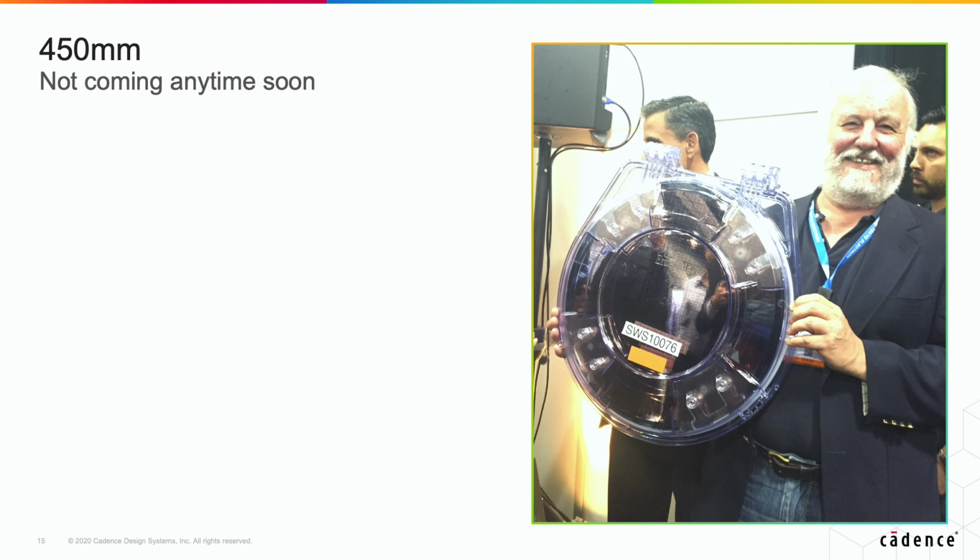There's an expectation, which is not happening anytime soon, but I've got a neat photograph of me holding one, of 450, which is huge. That's an 18-inch wafer. But the equipment for building it is so expensive, and the volume required for a fab to use those wafers is such, that nobody expects it to happen anytime soon. And it requires the whole industry to move. It's no good just one equipment manufacturer building 450 millimeter equipment if you don't also have blank wafers and testers and everything that can handle it. So the move from 8-inch to 12-inch was pretty traumatic.